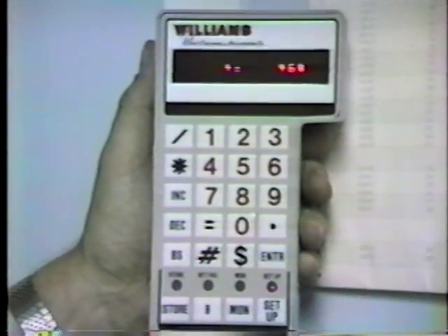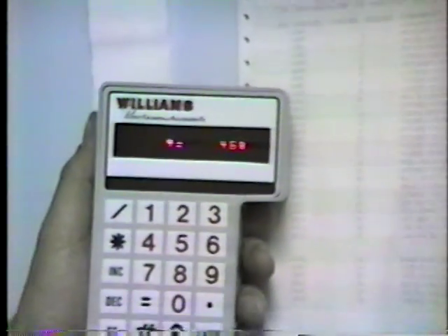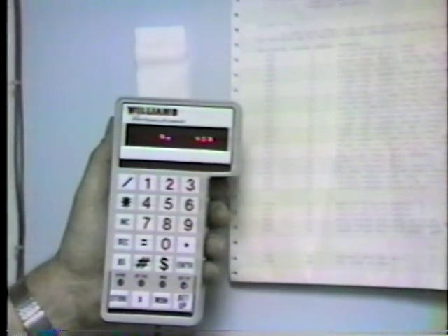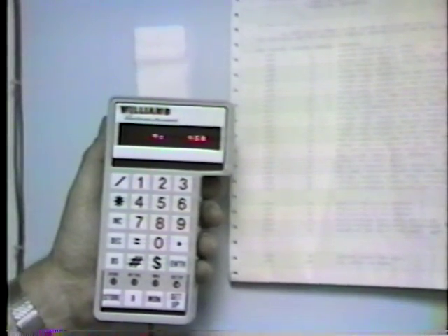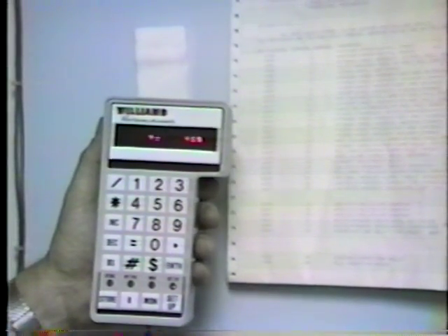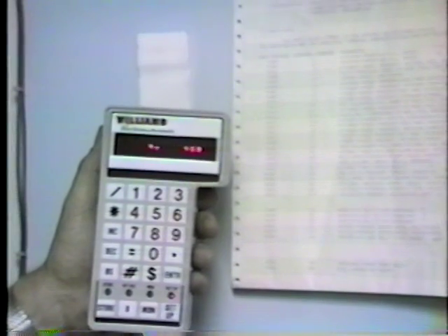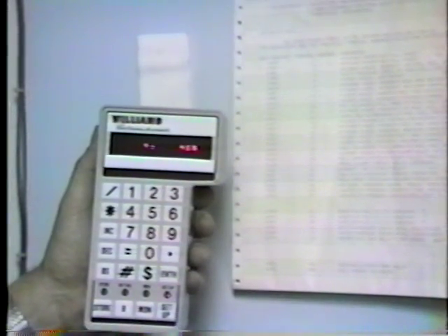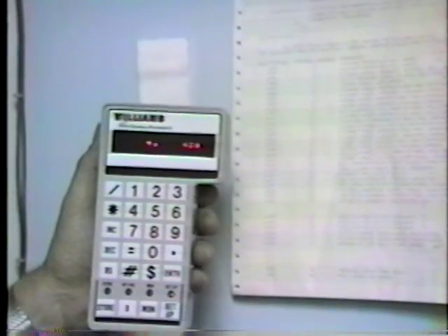Okay, 4 is 46, and 4 up here says the delta pressure ideal at minimum speed. That means we have a target of 46% of a 15-inch scale, which is, I believe, about 7.8 inches.